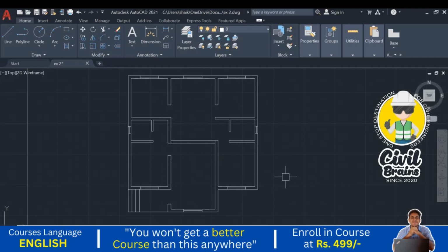After that the wall will come. So that whatever load comes, it will transfer evenly. If your wall is bigger and your plinth is smaller, then what happens? It will not easily transfer the load. There is a chance of imbalance of the loads. So that's why the plinth is kept a little wider than the walls. So that projection we need to show here.